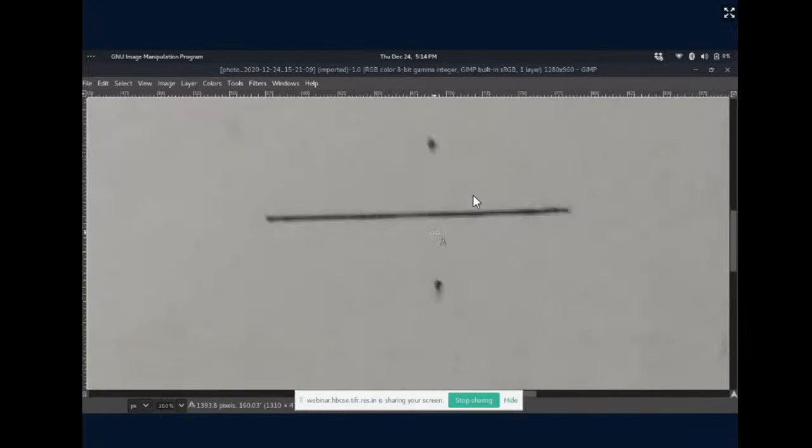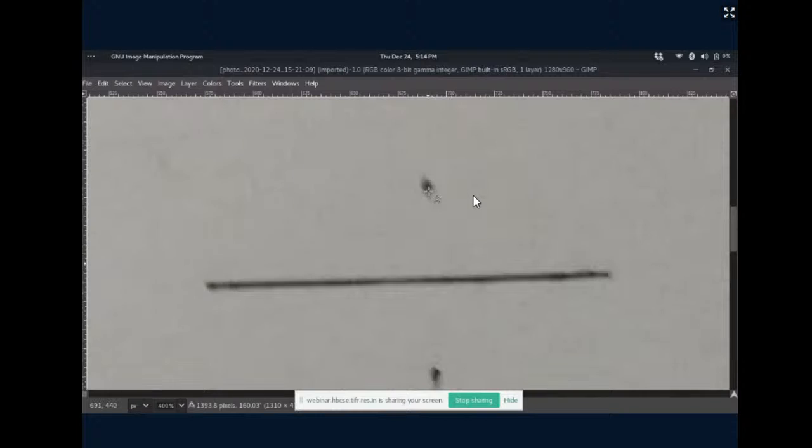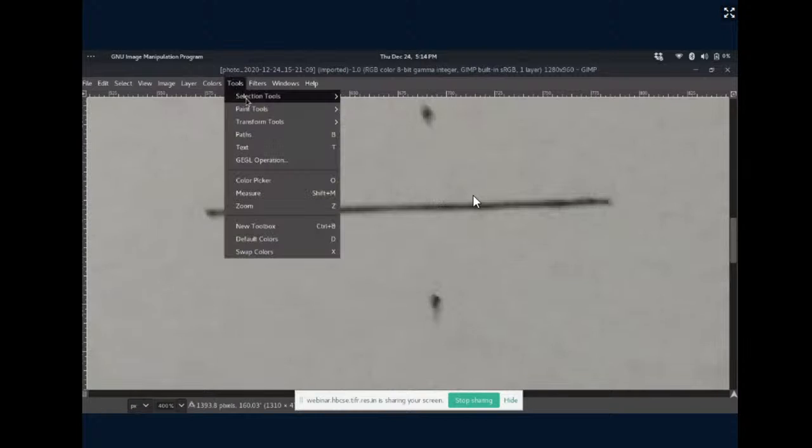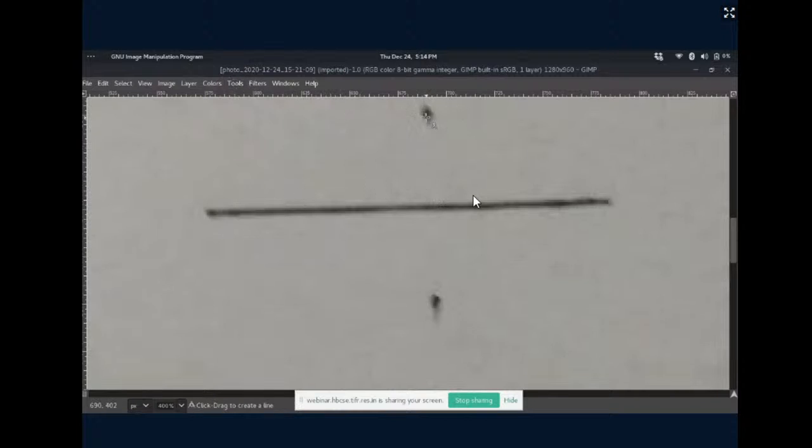It's the same image, but a different resolution. Again, I will do the same thing: go to Tools, go to Measure, and select the point. Now you can see that the 1 centimeter which we were seeing earlier is made up of how many pixels? 100 pixels. So we get a much finer scale with a higher resolution. The better the resolution, the finer the scale you have, to get a precise reading.